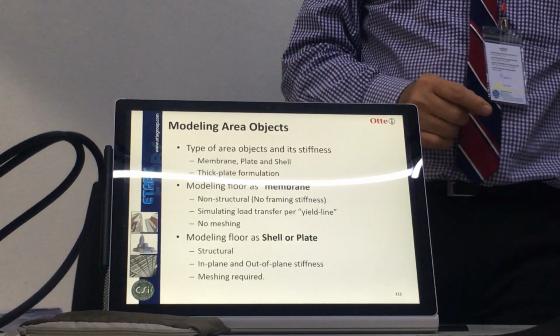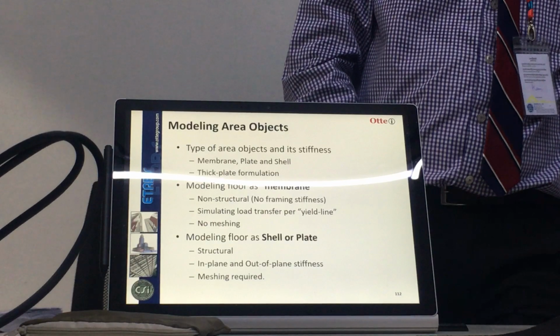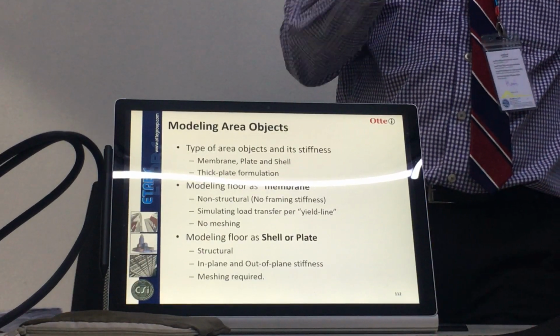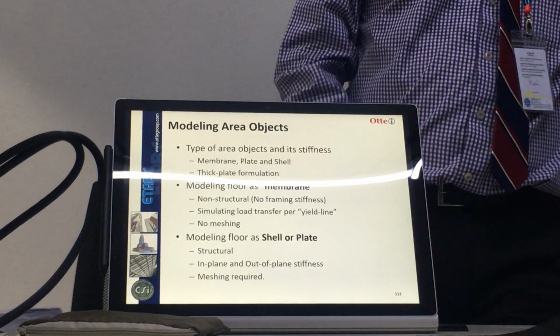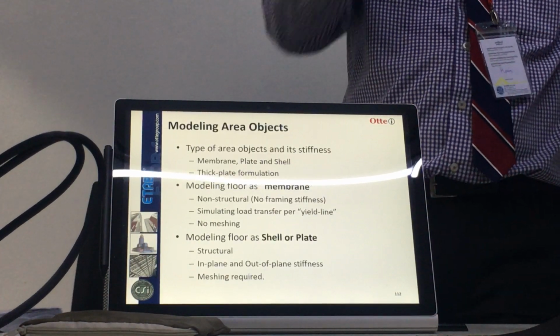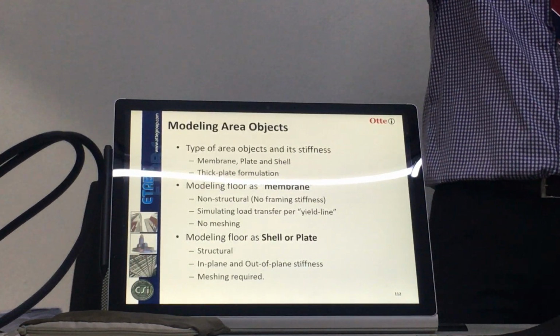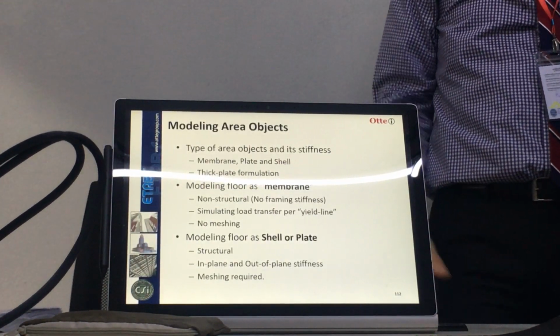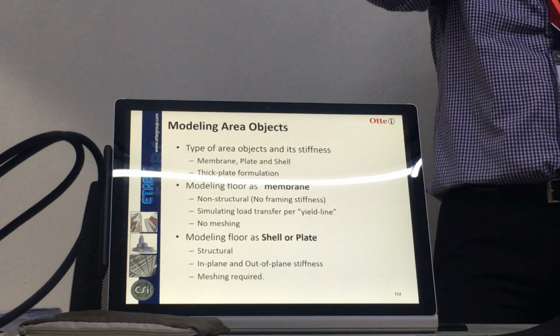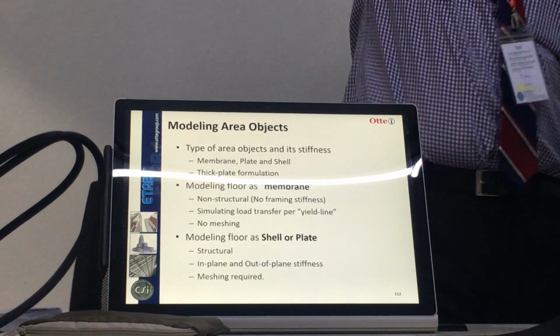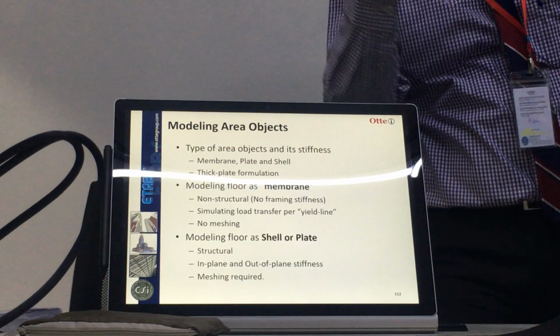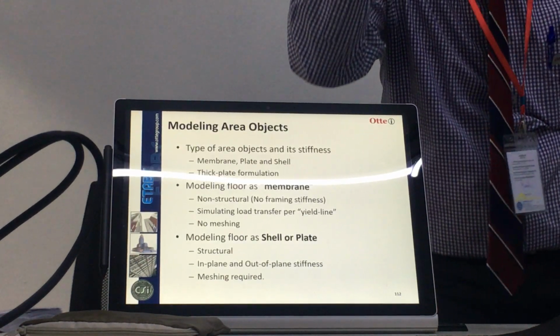Now I can see the buckling of my top flange. Yeah? If I use a line element, I cannot check the buckling. I can only estimate. But now I can do that. But if the I-beam is very big, a huge one, a girder, right? I may change it to solid. I can see the top fiber actually yield first and then migrate down.